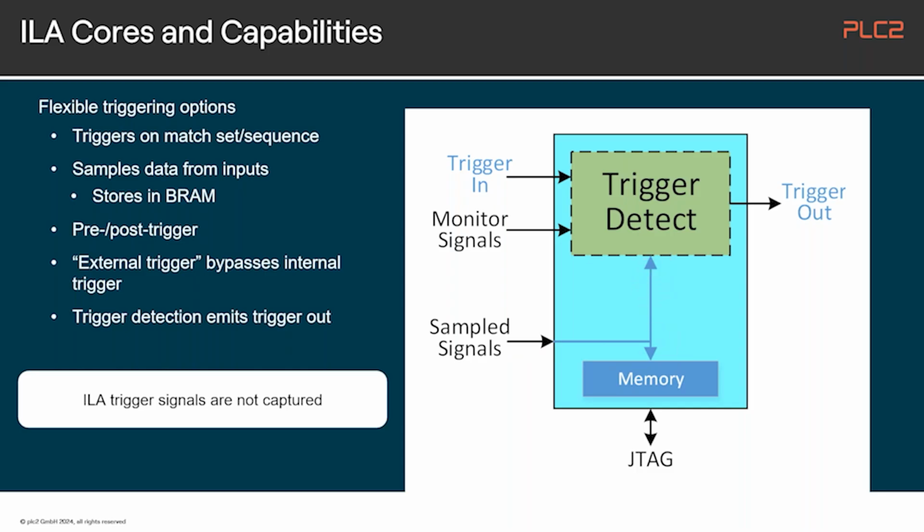But in this way and in that way can also be exclusive if you like, which means you can also define signals which are purely only used for capturing or purely only used for triggering. By default, both sides will be enabled.